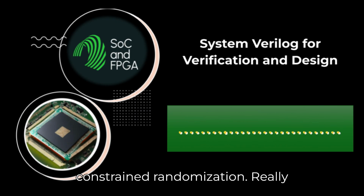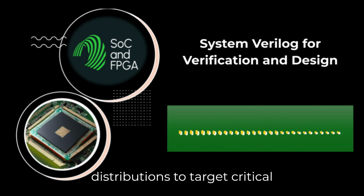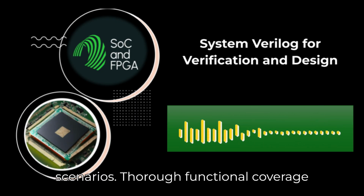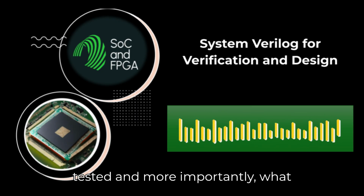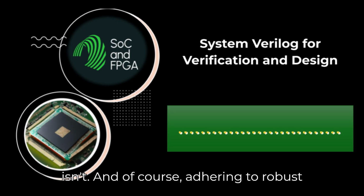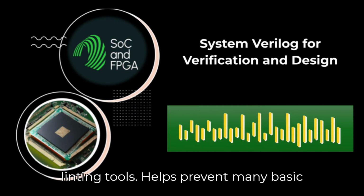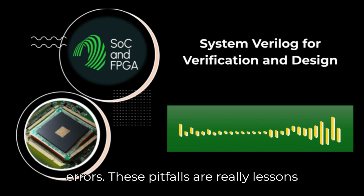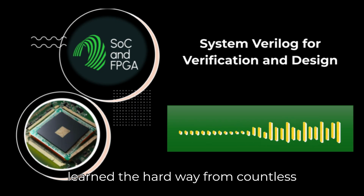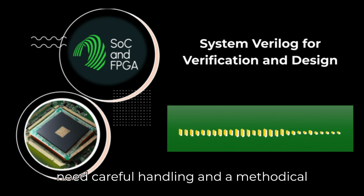Right. Effective constrained randomization, really thinking about your constraints and distributions to target critical scenarios. Thorough functional coverage analysis to systematically measure what's tested and, more importantly, what isn't. And of course, adhering to robust coding guidelines and using static linting tools helps prevent many basic errors. These pitfalls are really lessons learned the hard way from countless projects. Even the most powerful tools need careful handling and a methodical approach.